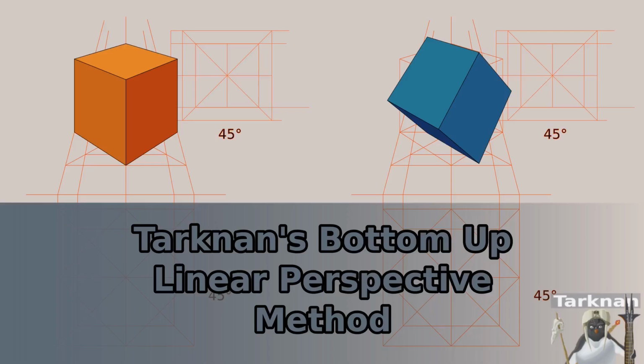It should be noted that this method is better suited for traditional drawing, whether freehand or using a straight edge. Second to this, Inkscape or an equivalent vector graphics program would be the next best option. In the coming examples, these basic steps will be performed and generally outline the process for the construction for the bottom-up method. Number 1, draw projection under the perspective drawing. Number 2, draw bottom plane and projection.